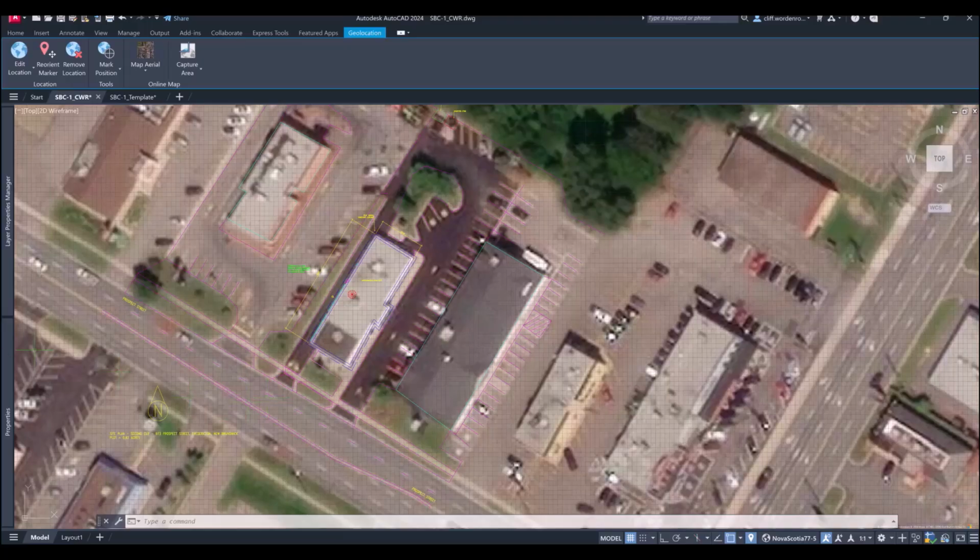If we go back to the assignment instructions, some of the things that I want you to do is draw the footprint of the building. The footprint of the building is the outline. You'll see this blue line, and you'll see that there's an offset around the outside that's 600 millimeters from that. I started with the outside of the building, then offset this one to go around the outside. I think this other line here is the roof plan. The roof actually extends over top of the walls itself. So that's what I'm showing there.